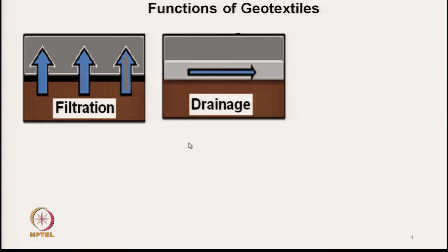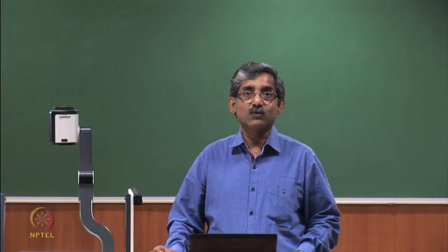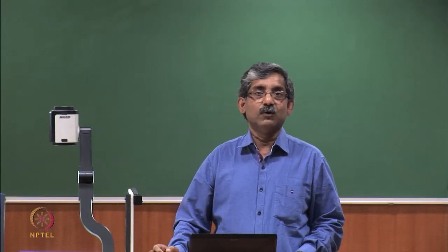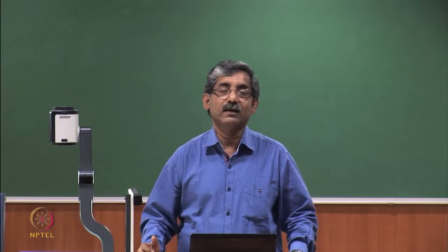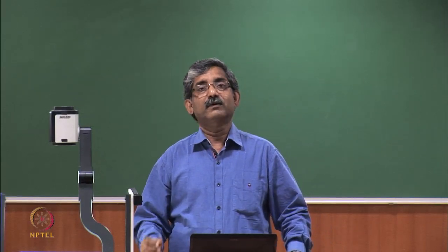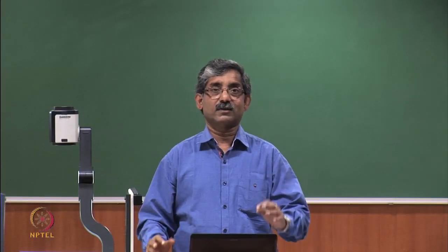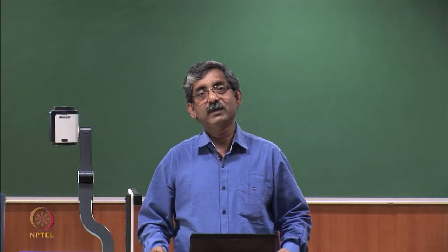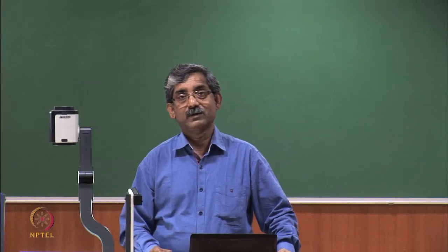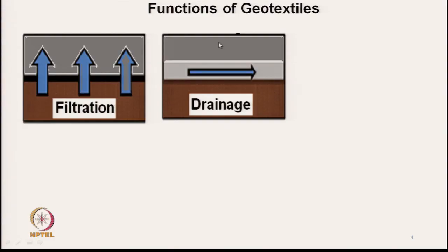Next function is the drainage. It is also a very important function, where geotextile needs to drain out the excess water, so that accumulation of water is not there in a particular place, and if accumulation is there, then the strength of the structures, that is soil structure, will be dropped. So, the drainage behavior is extremely important.